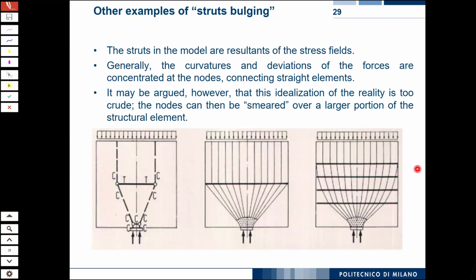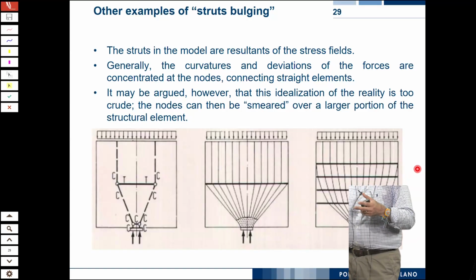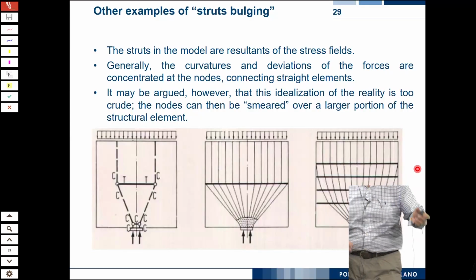So this reinforcement is just to take that horizontal component of the stress which is distributing, which the concrete will not take because it cracks, and you must put the reinforcement there. So that is the mechanically justified reason for which, close to a concentrated force, close to a pre-stressing anchor, we put this confinement reinforcement, because we have to absorb the transverse tensile stresses which arise because of the diffusion of the compressive stress field.